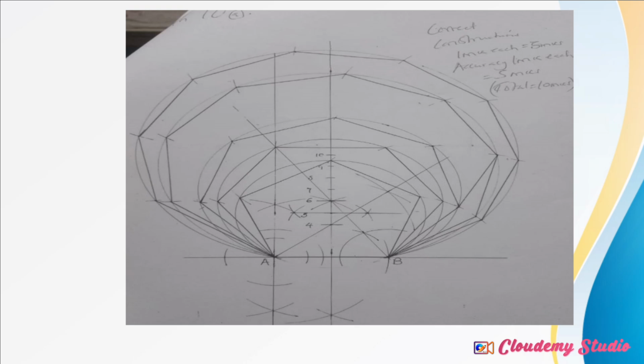You stretch your compass to at least 3/4 of that line, or because the measurement is small, you can just use points A and B. Using the same measurement, make an arc above and below the line, standing at point A. Then, without altering the measurement, standing at point B, you also make an arc above and below the line. So there will be 2 arcs, one below and another above. Then you make a straight line by joining the 2 arcs. You'll have bisected line AB and gotten the midpoint, so you can label that midpoint as M.